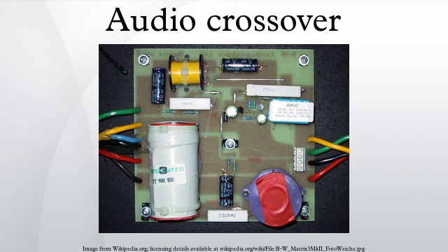In case a, the usual situation is that the derived low-pass response attenuates at a much slower rate than the fixed response. This requires the speaker to which it is directed to continue to respond to signals deep into the stop band where its physical characteristics may not be ideal. In case b, both speakers are required to operate at higher volume levels as the signal nears the crossover points. This uses more amplifier power and may drive the speaker cones into non-linearity.